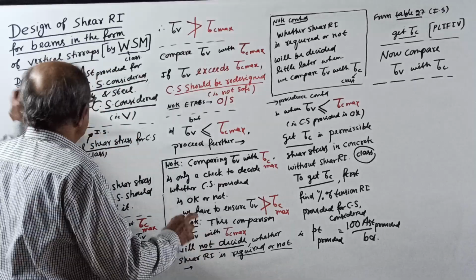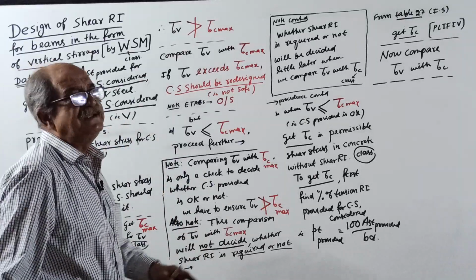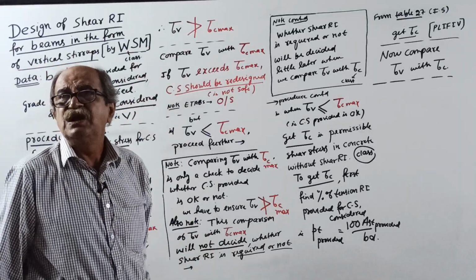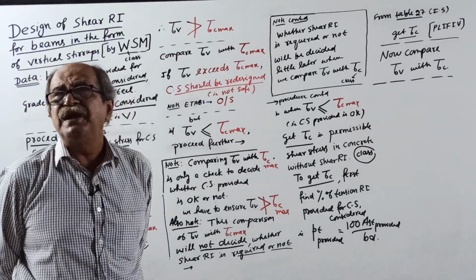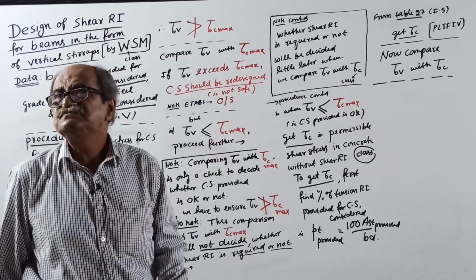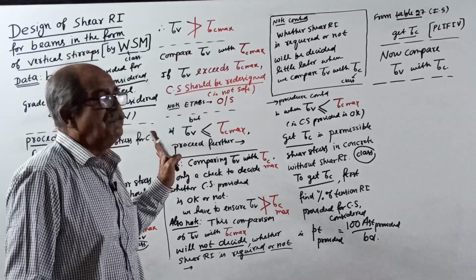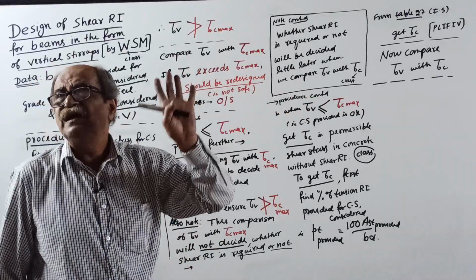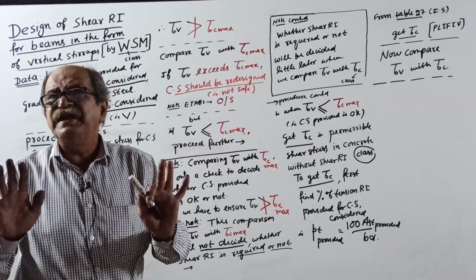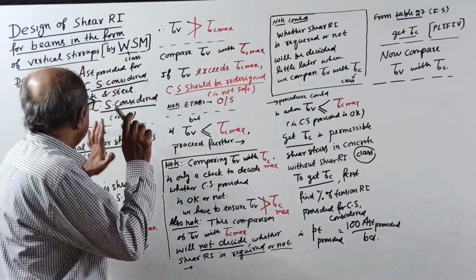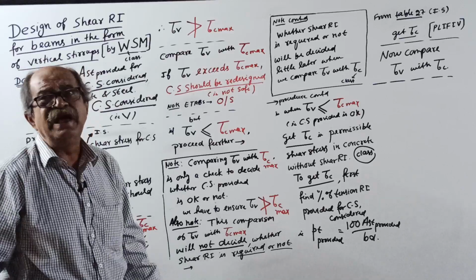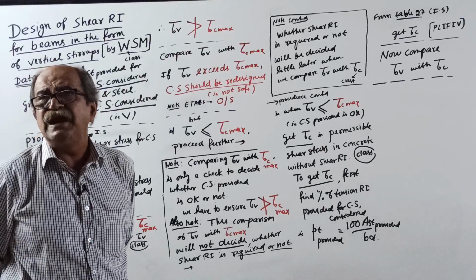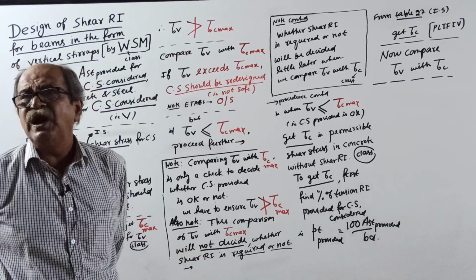See, a term called V will come. In limit state, Vu. Then a little later a term called Vs will come, Vus. Sigma sv will come here, 0.87 fy. Therefore, it is identical. So correctly go through the working stress method. What happens is, unknowingly, you are studying for limit state. But again remember, I will upload for limit state.